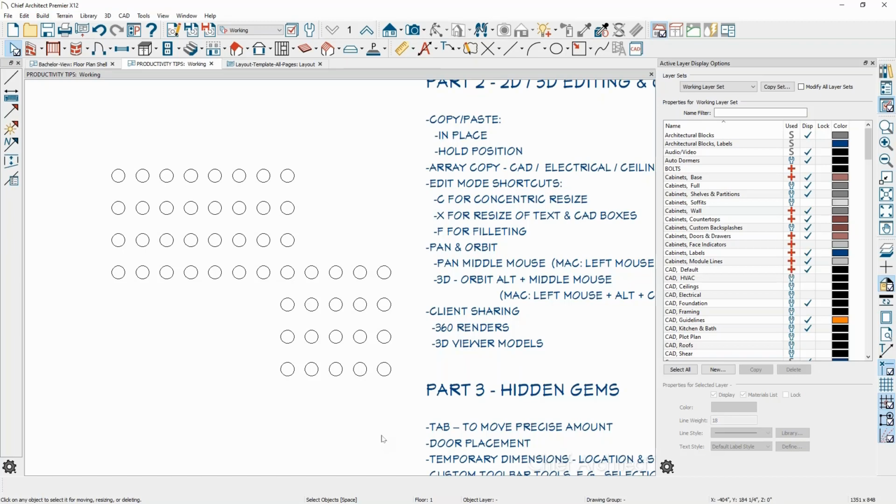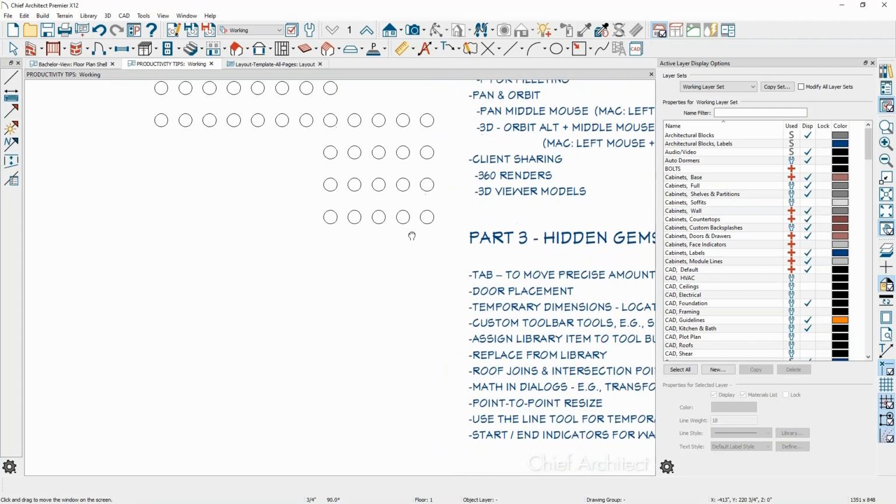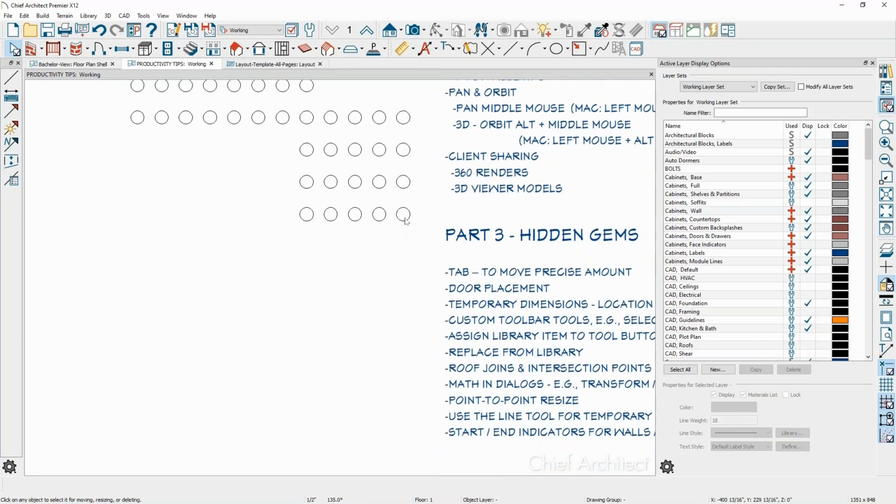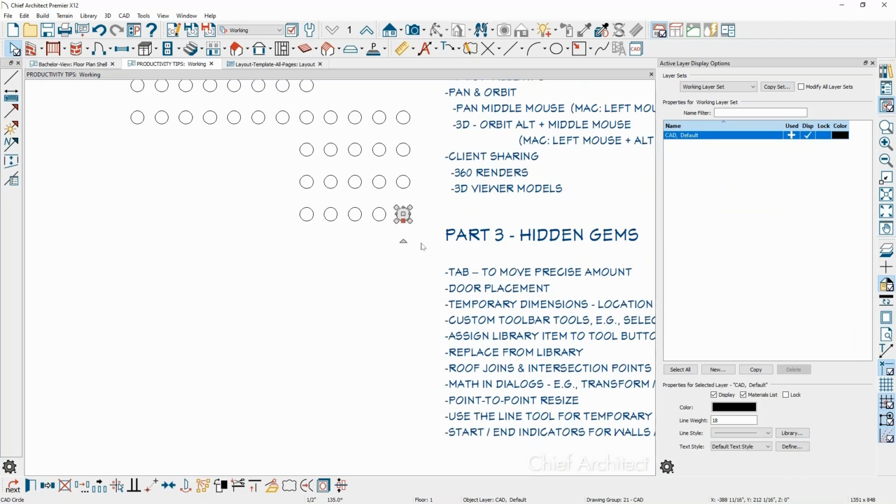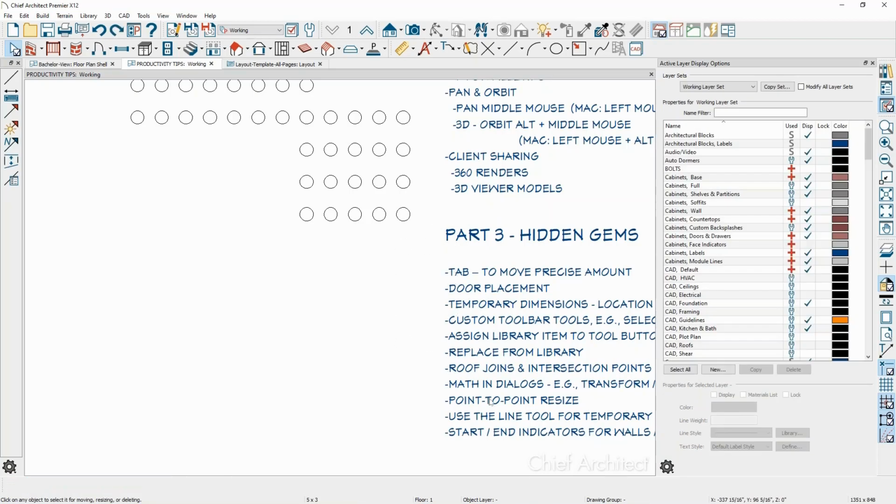Okay, can you show me that again? Sorry, there was something that popped up on top of the screen. So the interval is already defined in this case, 18 by 24. And it's already defined for trusses at 24 by 24. If you're not planning on changing that for the next operation, you never have to go back into that again.